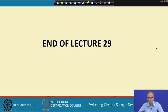So, with this we come to the end of this lecture. What we discussed in this lecture are some, as I said, unconventional ways in which you can represent some functions using AND and XOR gates. We saw how we can realize any arbitrary function using Reed Muller expression form, either in uncomplemented variables form or in the so called fixed polarity form, where some variables are complemented and some variables are uncomplemented.